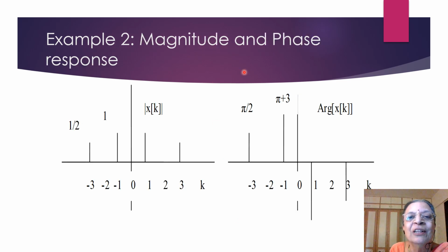So the corresponding magnitude and phase response I can write. The frequency terms are 1 and 3. This is the fundamental and this is the third harmonic. Then we are replicating it on the negative side also, because we are using exponential terms. Otherwise, negative frequencies have no meaning. Similarly, if I am plotting the phase, for this the phase is negative, and in this case, the phase is positive. Okay. So this is how the magnitude and the phase plot will be plotted.